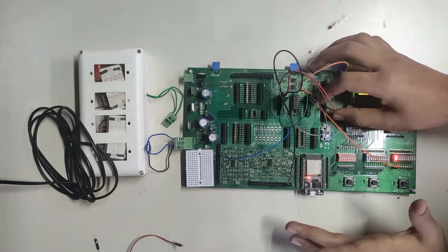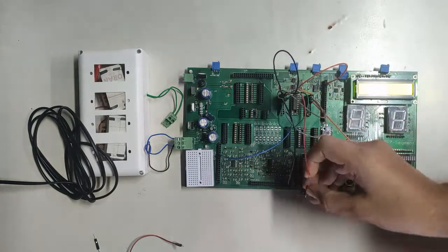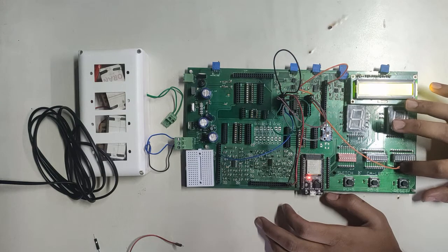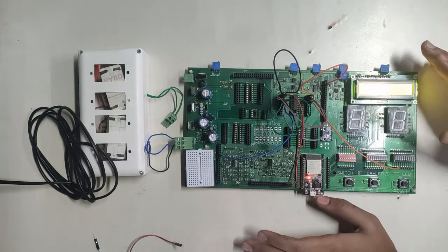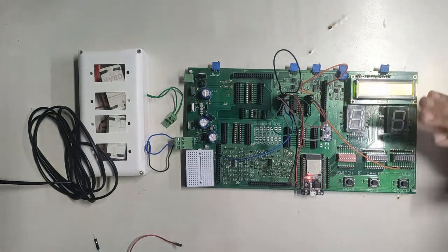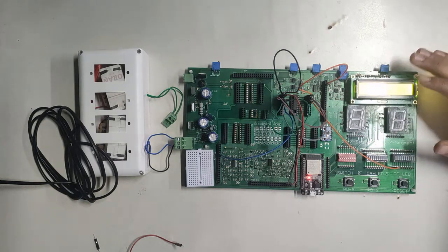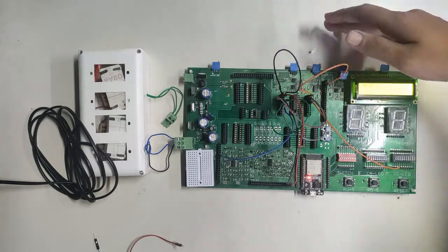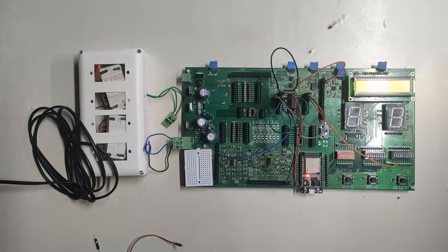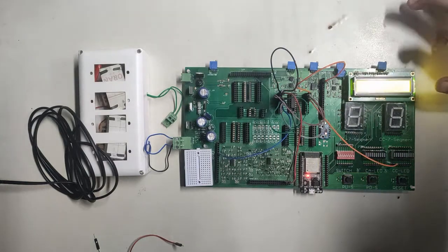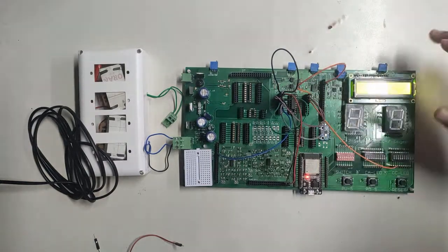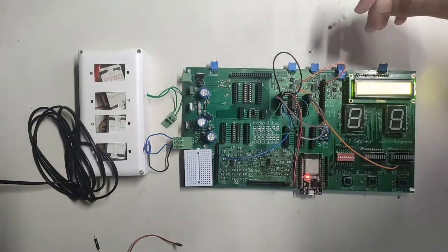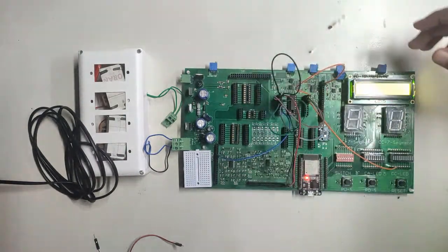Now what if both the inputs are logic 0? Then let's check it. As both the inputs were logic 0, the output is coming as logic 0. So these are the operations of nothing but the OR gate. By this we can say that we have verified the implementation of the OR gate using NAND gates. We have seen all the operations, and these are the operations of nothing but the OR gate. So we have implemented the OR gate using the NAND gates.